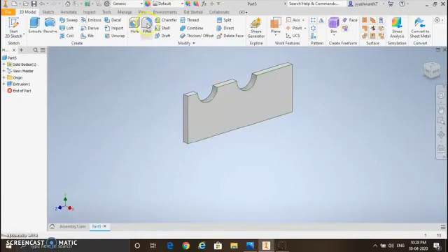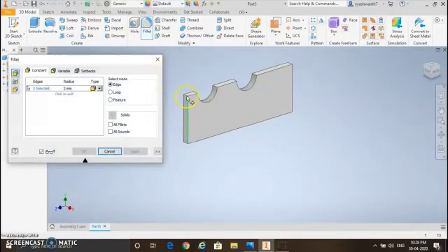We can make the fillet for the edge of the housing. As the fillet is only 2 mm, it is not appearing on the part. Let's make it 10. It is a small fillet, absorbed. You can see, hit the arrow. Now 15 and apply. Close. Save the file for further use.